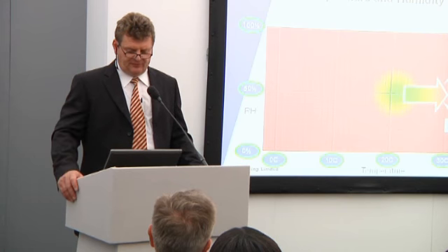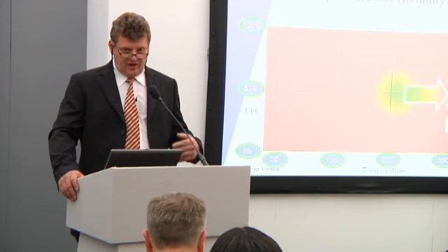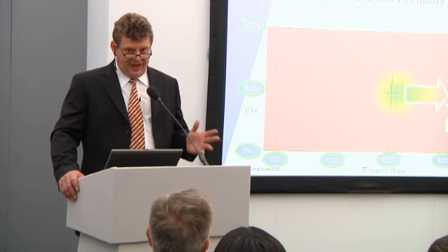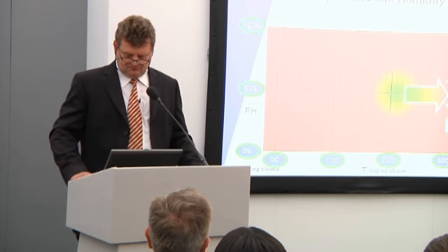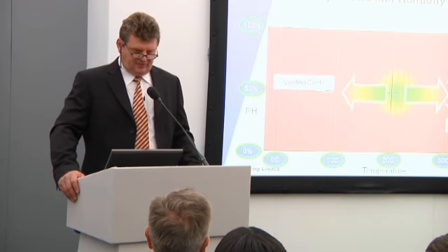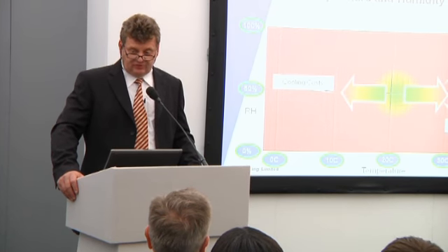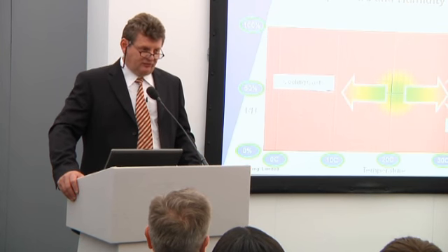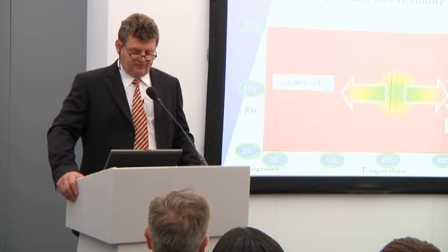Things will blow up at high temperature. What a lot of people don't appreciate is if you increase the temperature of air going onto a server, the little fan starts to speed up and can consume an enormous amount of energy itself. Low temperatures: most low temperature limits in the standards are economic, not technical standards. These standards are set to stop people running their refrigeration equipment too cold and losing further performance.